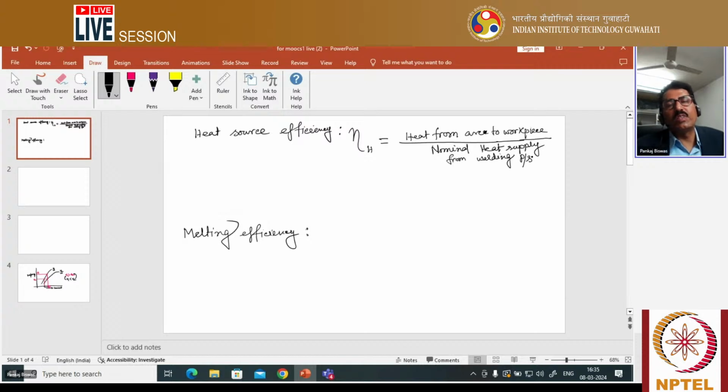That loss is due to different reasons: due to the resistance of the arc, due to convection, due to heat absorbed by the resistance of wire. Also the electric wire and other things we use can absorb some heat. So for different reasons there can be a loss of heat. All the heat is not absorbed by the workpiece. You are very well familiar.